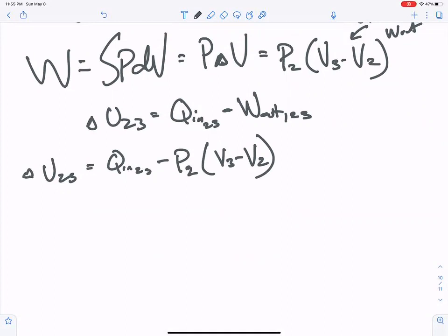But then the book just quickly plugs in without explaining much; they skip a few steps. Here's another step: you can relate enthalpy to internal energy for all cases, as long as you know the pressure volume term and the internal energy U term, that's what enthalpy is. And we use that when there's a flowing system, that PV term accounts for the flow. When there's a reacting system, it accounts for these PV effects due to reaction. That's why we use delta H in many cases. This is a third case where it's simply useful to combine these pressure and volume terms.